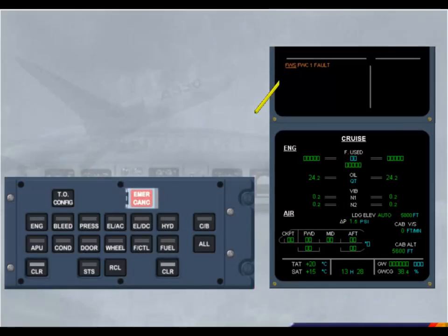To begin, we will look at what happens if one or both flight warning computers fail. For a single flight warning computer fault, a caution message will be displayed on the engine warning display. Notice that there are no blue action lines, so no crew action is required. No system page is called because there is no system page for EIS. Clear flight warning system.